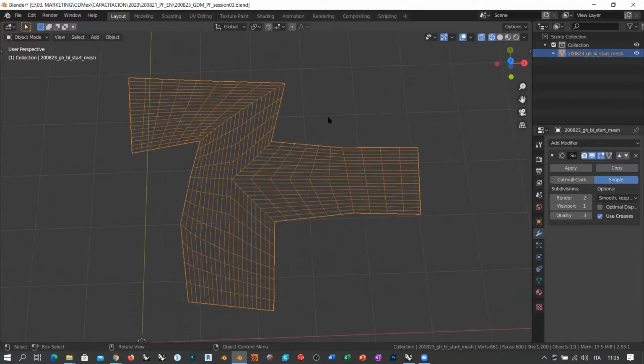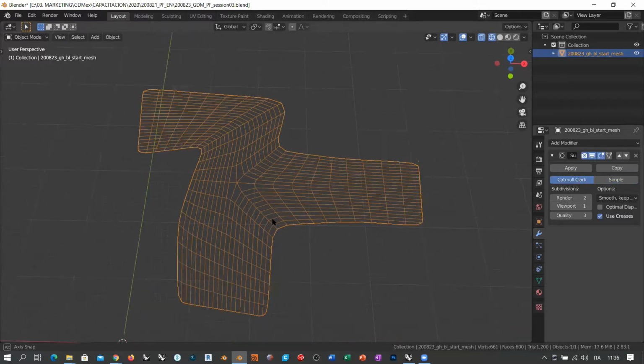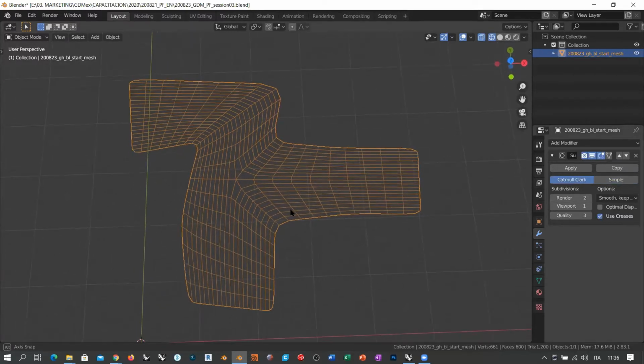So in the end, we start having a higher resolution version of the same mesh, but with a more regular aspect, and of course with the loop topology that we were looking for. And also, if we go back to Catmull-Clark, you see that polygons are a little more regular. So if you want a more uniform behavior in the two directions, you better adjust the aspect ratio of these polygons. But nevertheless, you can always work with the mesh that I already sent you.